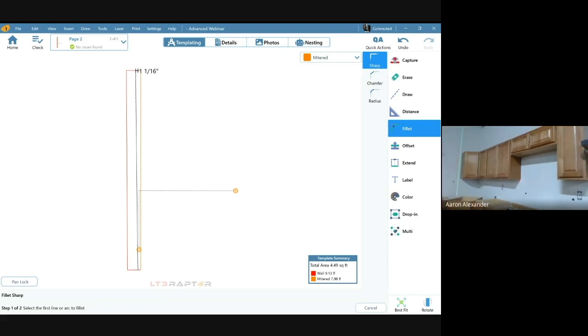Now, if it's not a cavity situation and it's a flush panel on the bottom here, then I can use two of these, right? We give you two of them in the kit. And then what we're going to do there is we're going to take our tape measure and we're going to set that at a distance. No different than the technique we're using here with our pin block, shooting a 1/2 inch line and offsetting it down a 1/2 inch. We could take these targets and we could take our tape measure and I could set, say, that bottom gap at like a 1/2 inch right there.